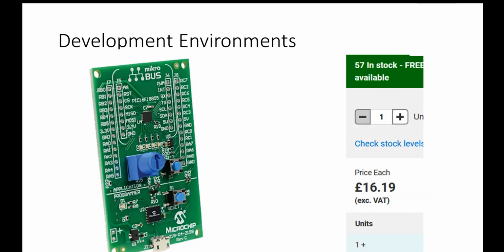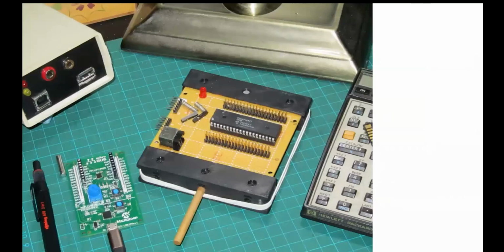What I'm about to explain to you about what I'm doing will take me half an hour to explain. It actually takes about 10 seconds to do. You can change something and press generate, press build, and as it builds, it copies it into the F drive or the H drive, and it puts it on the board, and the board starts. It's instant. You don't need to go through all that. Is my PICkit 3 connected to it? Have I got a 100 ohm resistor in series? None of that. It's really instant, a really, really useful thing. However, I've also got its big brother.